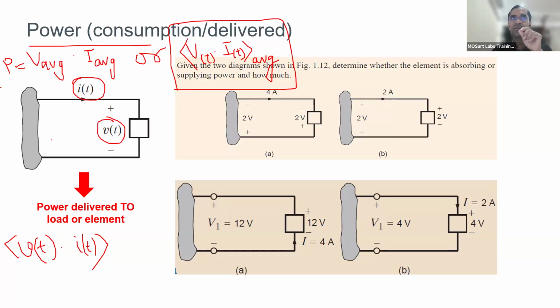Okay, so if the variation is smaller, then whether you do the first case or the second case, approximately the answer is the same. It will be no different. But if the variation is large when compared to the mean, then the second one will give you a more accurate result. The average power is the average of the instantaneous power, P of t. You take the average of that term. Okay, so the thumb rule is whenever you want to calculate average power, write down the power equation. So it is V of t into I of t, then take your average.